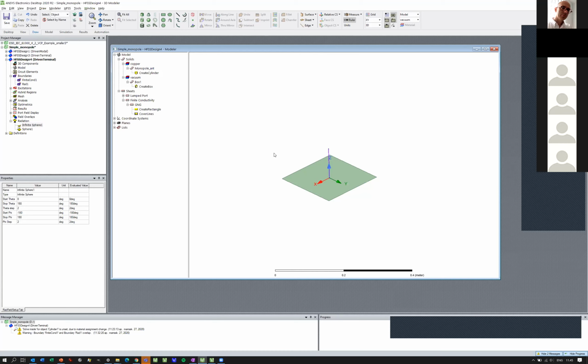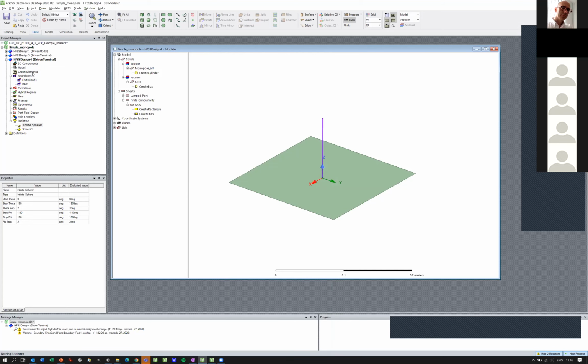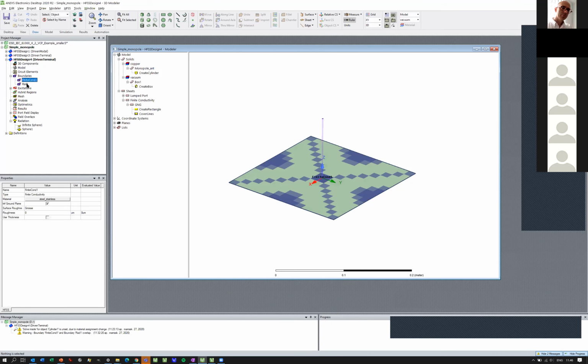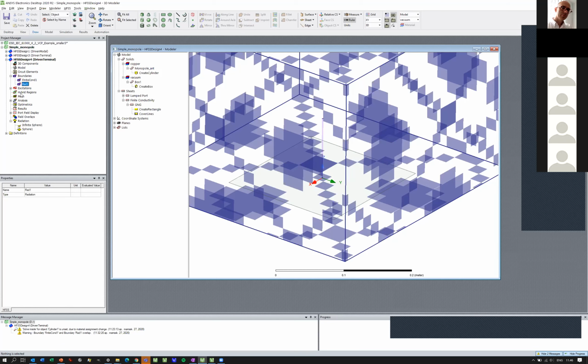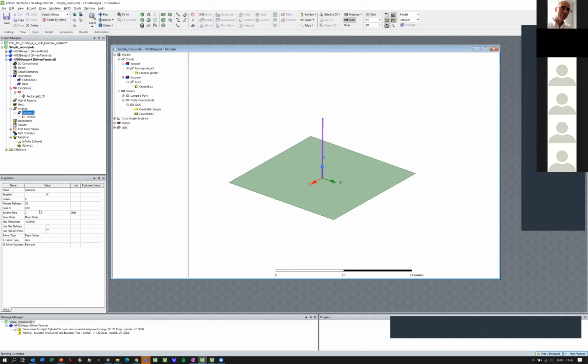So these are all the setups I need to do in order to simulate this kind of simple setup. I was drawing the CAD files, adding my ground reference, radiation, giving the excitation here, and adding my frequency, which is 2 gigahertz, and so on, and the sweep.